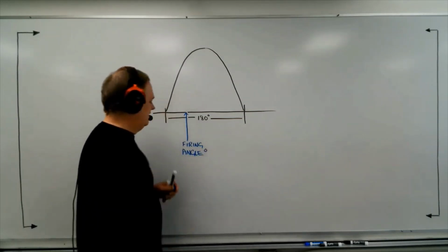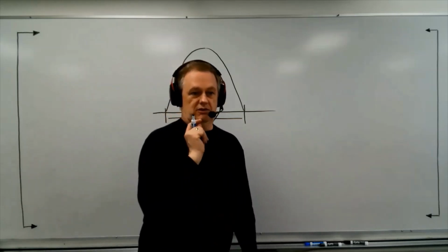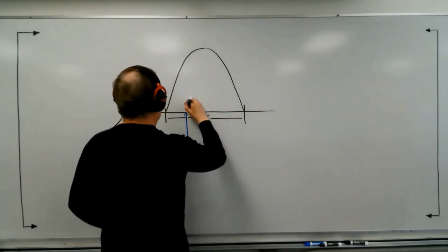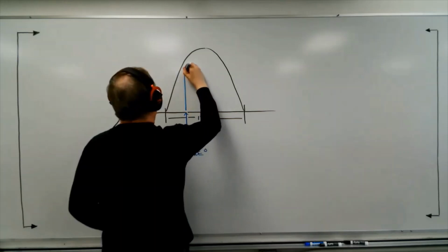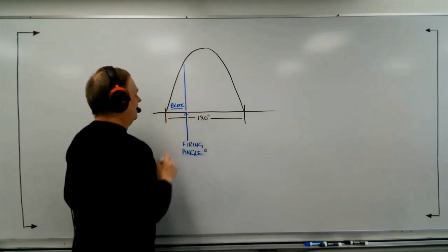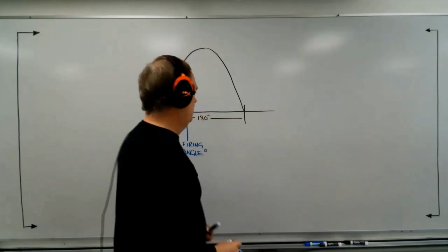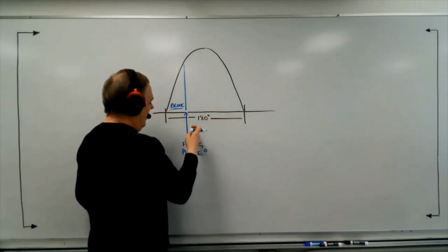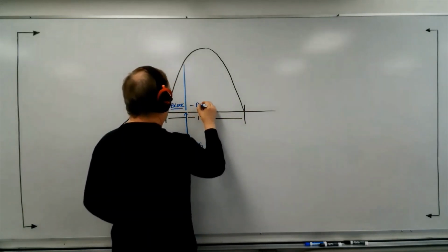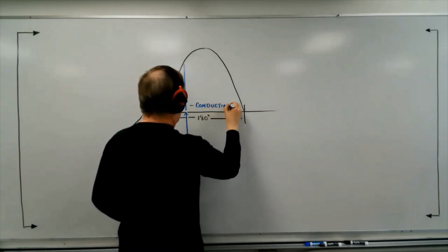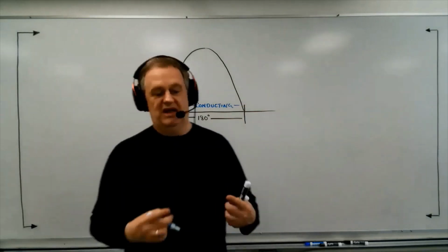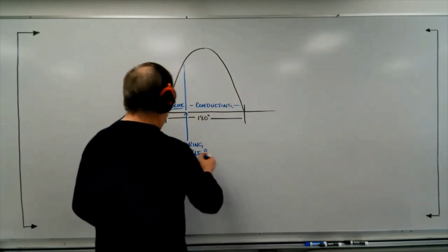Okay, it's the angle in degrees where we apply the trigger pulse to the gate and the SCR turns on. That is the angle. And so what we could say is everything up to this point is blocking. The SCR is not allowing current flow during that period of time. And everything that happens after that, until the end of the alternation, we would call conducting. And seeing as an SCR is really only capable of managing one alternation, here's what we can say.